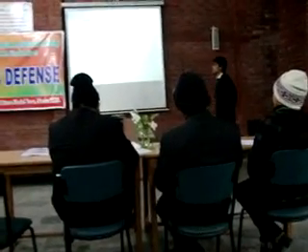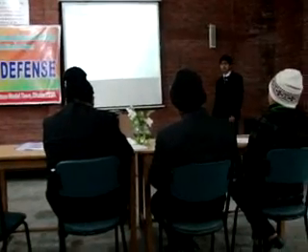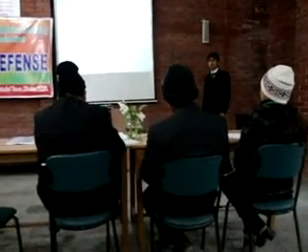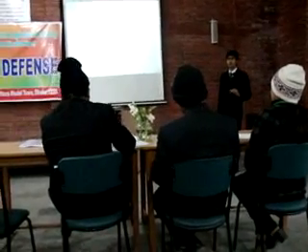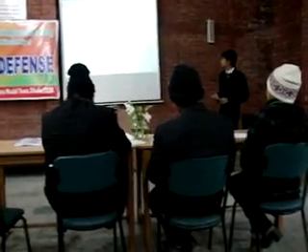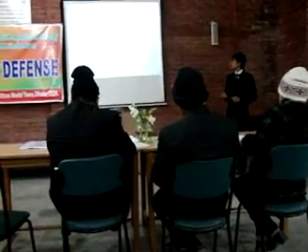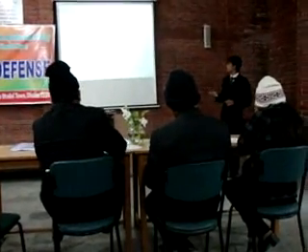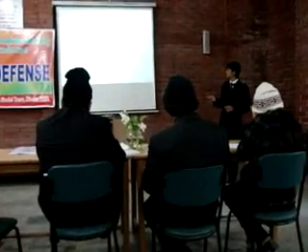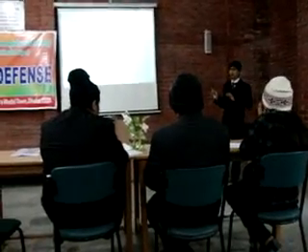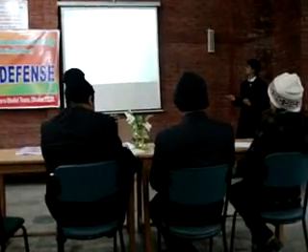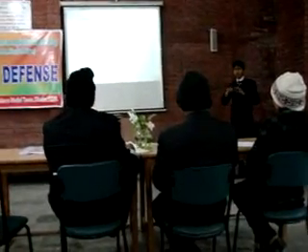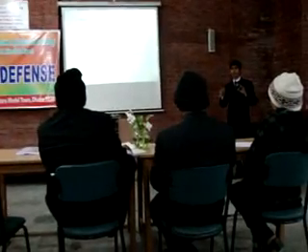Entering and running the program. When we design a ladder program, we have to download this program into the PLC by using a cable as a medium. When the download is complete, the download button is pressed, and we can download the program from the PC to the PLC. And here is the run button. If we press run, then this ladder logic program will run inside the PLC.